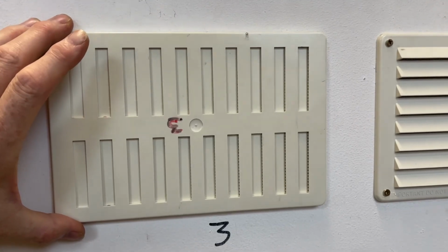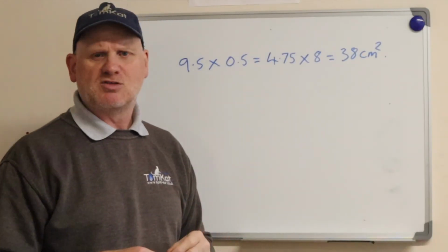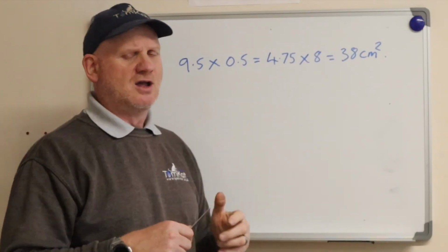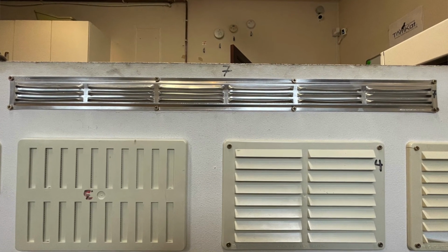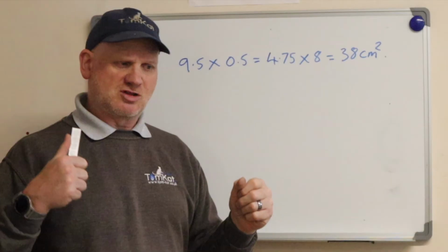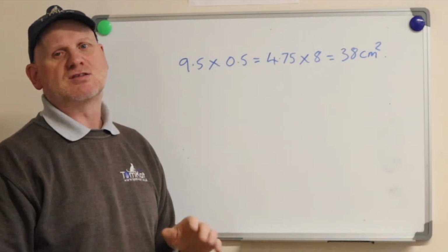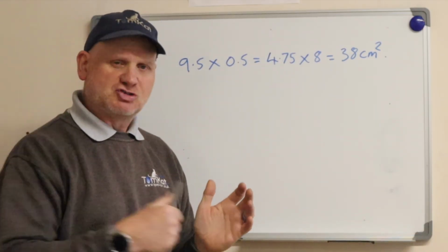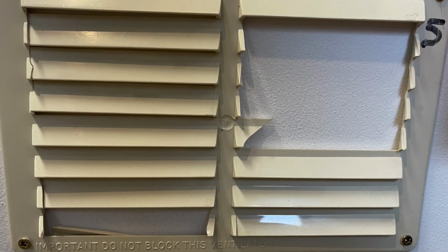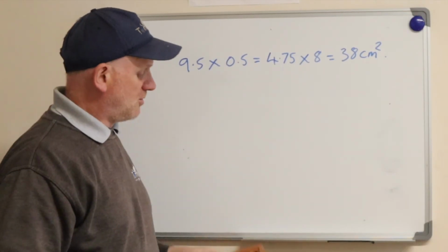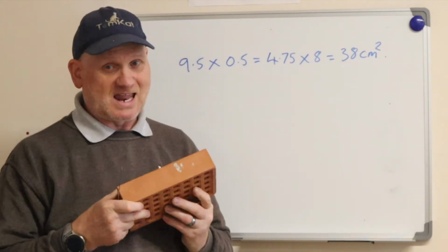Now obviously vents which are closable, vents with fly screens, are not allowed to be used on gas appliances. Also vents which are made of aluminium are now deemed the incorrect type, because if you punched it, it would flatten it and close it, so it wouldn't be any good. But if you punched a plastic one, it would break, so then you get a bigger hole, so it's not unsafe. Anyway, another one is the terracotta bricks, which aren't allowed now.